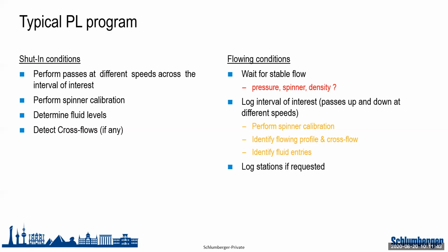Then the shut-in condition also helps us determine fluid levels. For example, where is the segregation between water, oil, and gas in the wellbore? And it is also the main condition in which we can detect crossflow. For example, we can detect if a zone that has a higher pressure is feeding into a zone with lower pressure. That is going to be mainly observed in the shut-in condition.